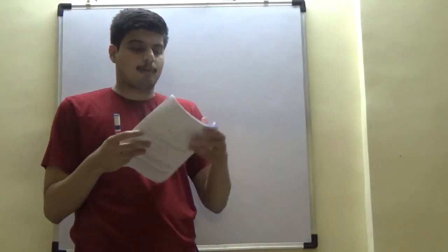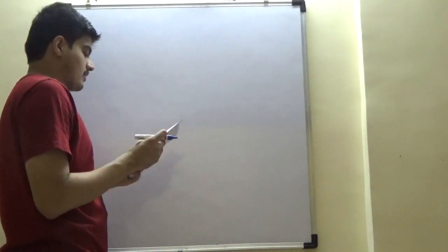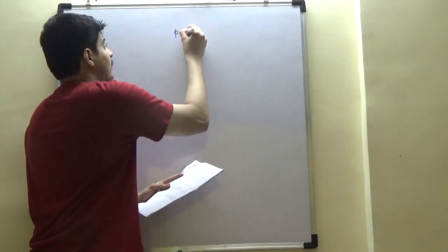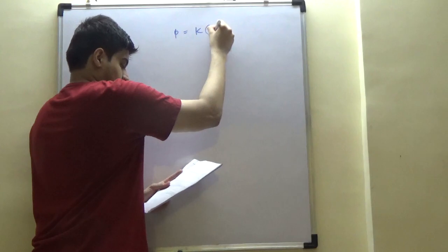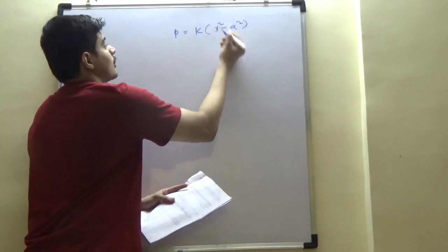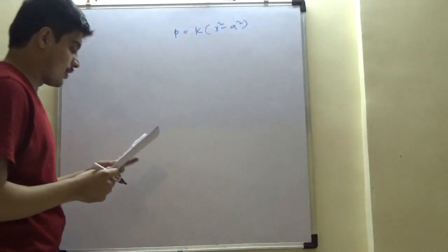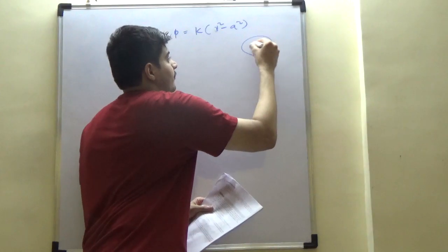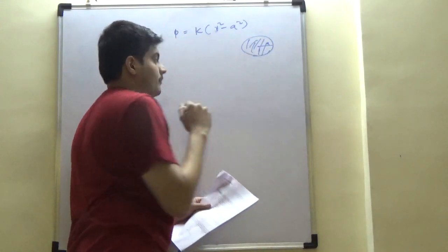The second practical problem which we will look at, we have already seen this, but we have to find out now. For a circular cross section, K(r² − a²) is a valid Prandtl's function. This stress function can be applied to a solid cross section which is circular in nature, of radius a.